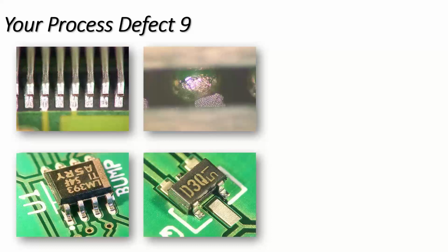There is quite a lot of data which comes out from CAD systems which is not right. And I have worked for customers where they had followed what they were told to do, but clearly the data wasn't any good. So what do you do? Use bad data, or use your own engineering expertise to modify the stencil data and give the customer what he really wants, a good product. So keep people in the loop, but please use your own expertise.